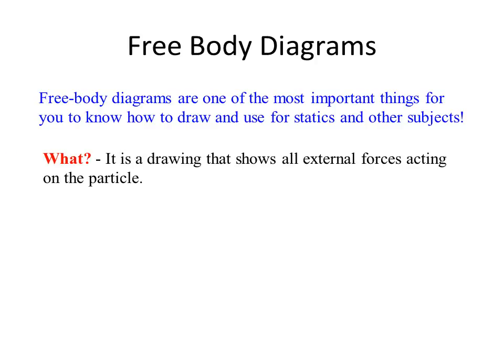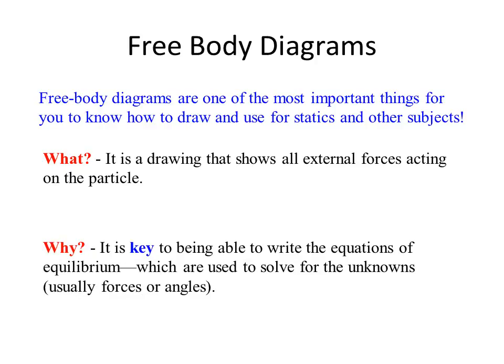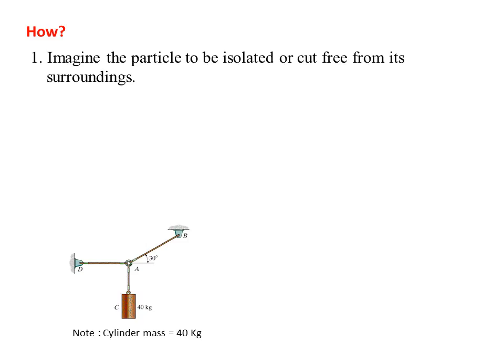What is it? It's a drawing that shows all the external forces acting on the particular particle of interest. Why do you do it? It's the key to being able to write the equations of equilibrium, to be able to solve for the unknowns, which usually involve forces or angles in our problem. How would you do it? That is, how would you draw a free body diagram?